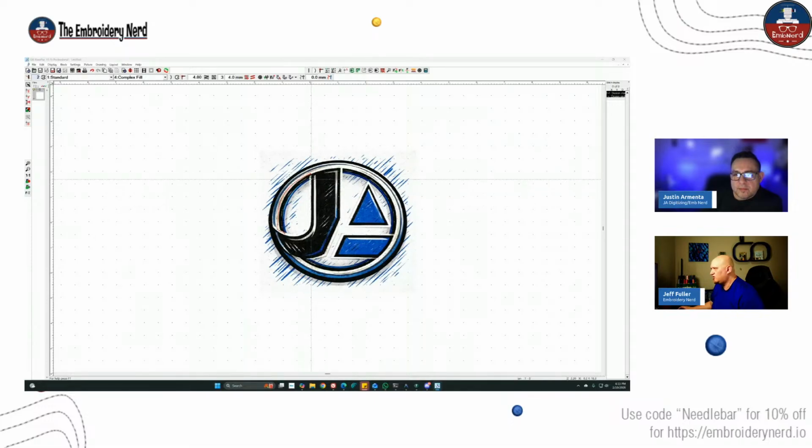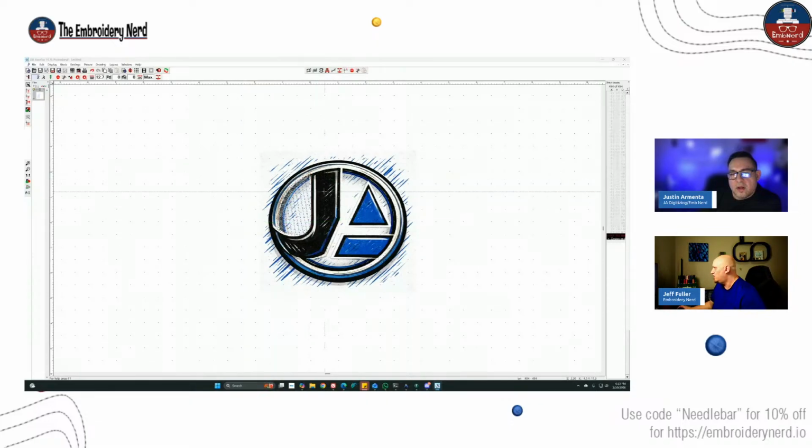And to do a corner node, it's a double click. To stop, you just have to double click. Right click brings up this sub context menu, which I find really helpful because I don't have to travel really far to get to it. I can just right click, bring that up, and now I can set my stitch direction. I can change my endpoint here and hit enter, and it's going to generate the stitches. And you can see how it generated that whole list on the right.